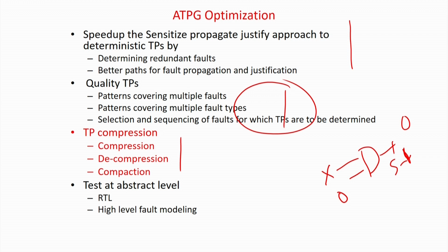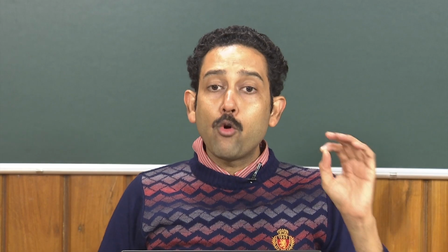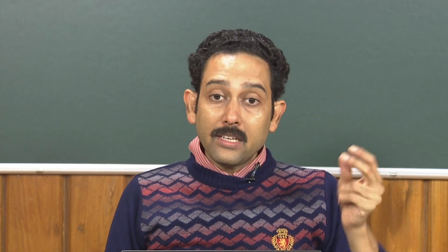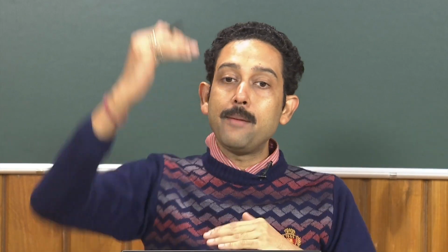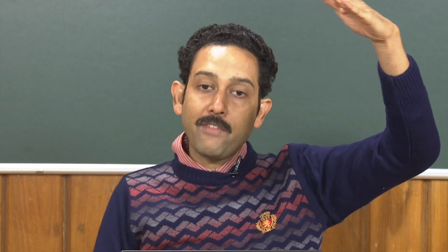If you take a large or general practical circuit example, such X's in the test pattern, which can be either 0 or 1, occupy more than 90% of the variables. That is a very interesting observation people have found. Now using those X's, can we compact the test pattern? If the input bit width is, say, 100 and there are a lot of don't care variables, how can we compact the test pattern? In that case it will be optimized in the sense that you can apply patterns of smaller bit width from a tester, so that you can save on the tester part. We will detail this by examples. That is the idea of test compaction or ATPG optimization: instead of having very wide test patterns, can we make them smaller in width? Smaller in width means fewer channels from the ATE, etc.